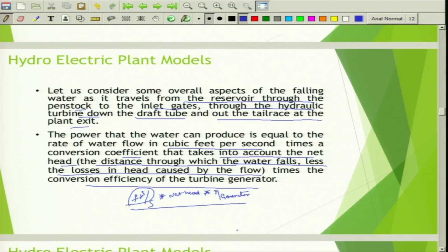There is a difference between the height of the forebay and afterbay, but during the water inflow there are many factors that need to be considered. There are friction losses in the penstock, and there could be spillage, some water loss. It's not that the exact volume of water is available for your electricity generation downstream. So to consider this aspect, we reduce the overall gross head. Let's say there is 100 feet, we reduce the overall head to 95 feet.